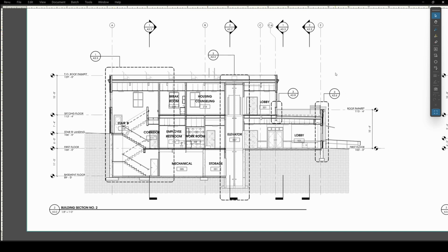It's up to you whether you want the grid to continue all the way through from top all the way down to bottom, or whether you want them to stop short. Same thing with your levels. But you'll want to see these grids because these grids will identify and hopefully help you create wall sections, which is the next portion of the set we're going to talk about coming up.